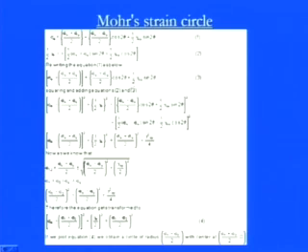So, if we take this term, it is the whole square: (epsilon x minus epsilon y)/2 cos of 2 theta plus half of gamma xy sine of 2 theta, whole square, plus the right side of equation 2. Since the whole square is there, this sign will be positive and you can simply square those terms. Now if we expand these by squaring, we can see that there are some cos square theta terms, some sin square theta terms, and some 2 sin theta cos theta terms.